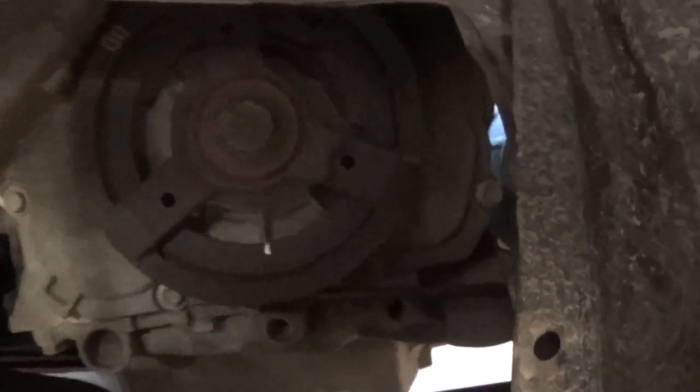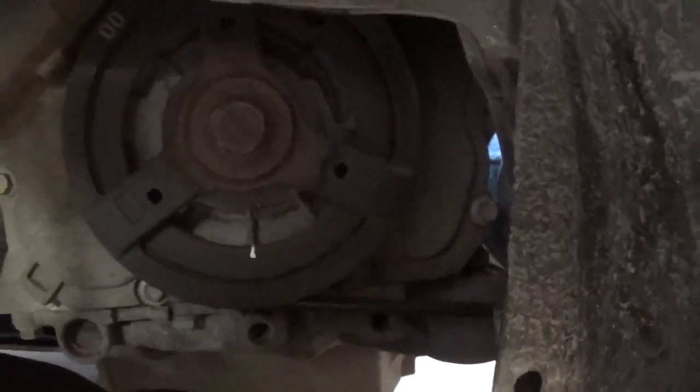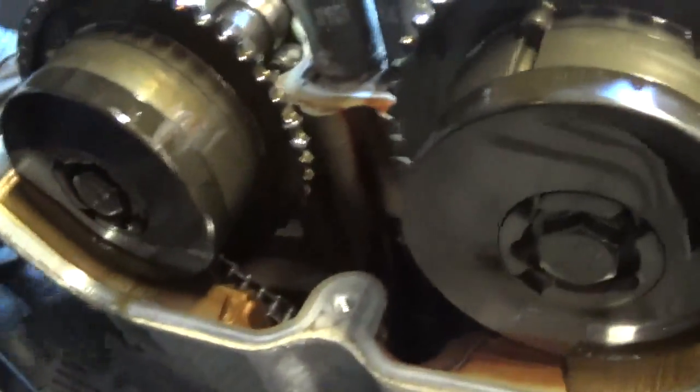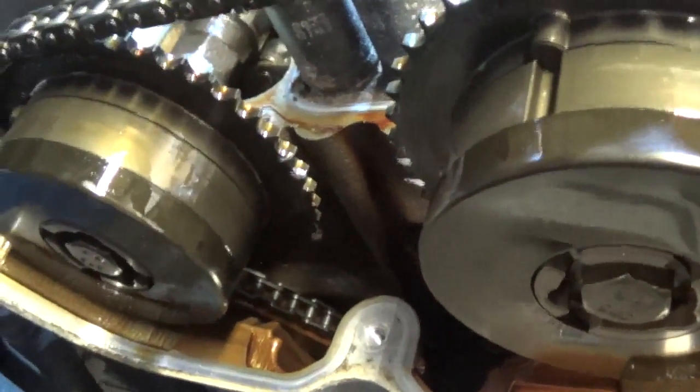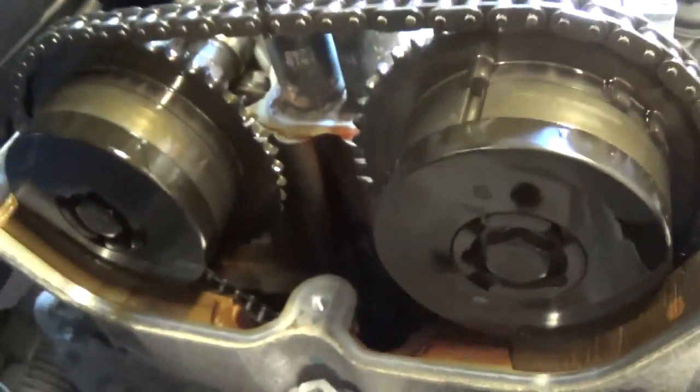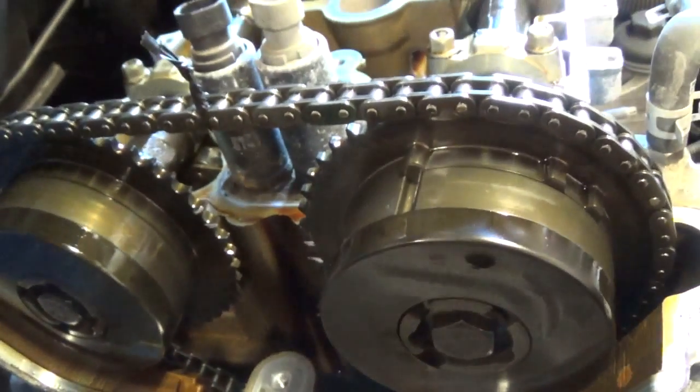Down here on the crank pulley, I got a little white mark aligned with that whatever aluminum protrusion. So that's where that's going to stay. Now we took the timing tensioner out, which lives right in the back of the head here. You can actually see, you can push that guide with your, ooh, well, I guess we jumped a tooth there, no big deal. So anyways, we're gonna take the camshafts out here and go from there.